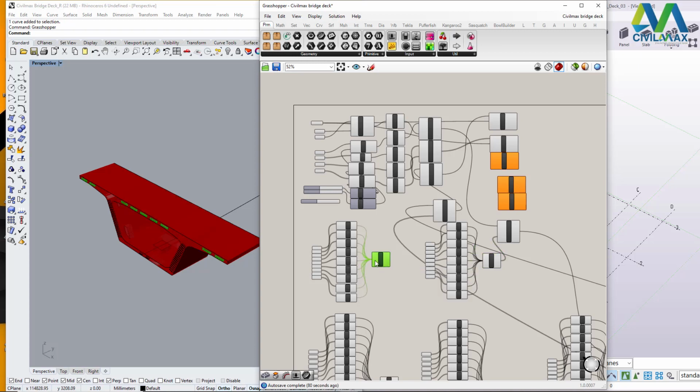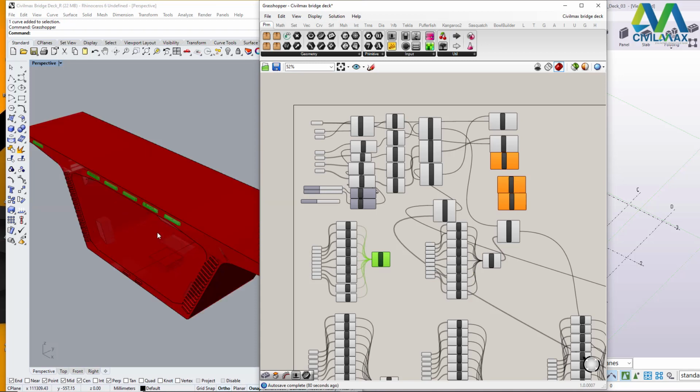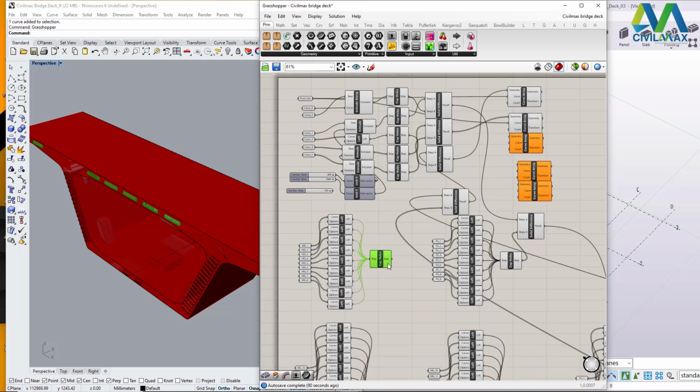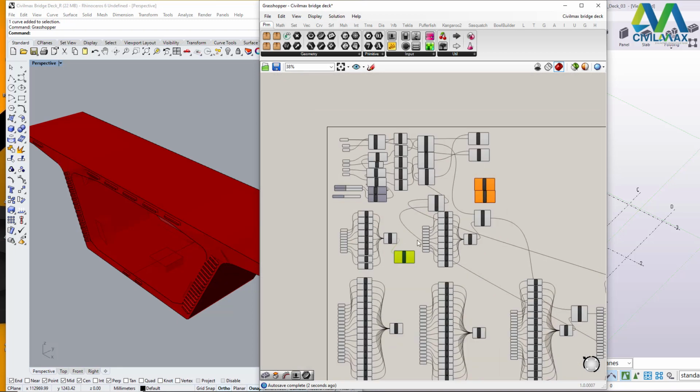So these ones haven't been connected with our concrete bridge deck. Now what we'll do, we'll just click on this or any of this, and drag it close. I made several copies because I knew that we'll need several of these. Now I'll click on this, then link this geometry to that, and also come here.